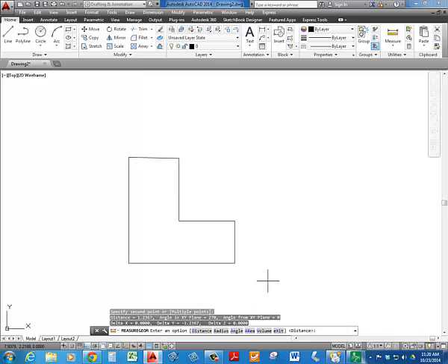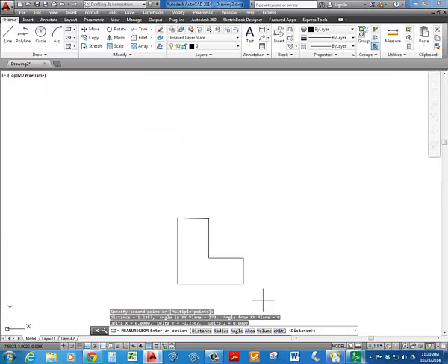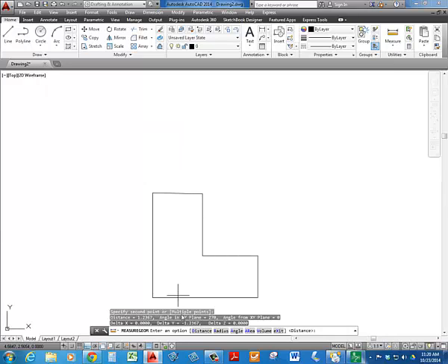So it gives you the feedback information. That's kind of like what list is. All right. Then if you want to know the angle, all right, it says specify vertex. So you can't just pick a line, okay? But you got to specify vertex. So you got to select a line, arc, or specify a vertex.